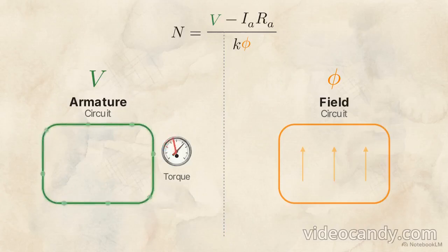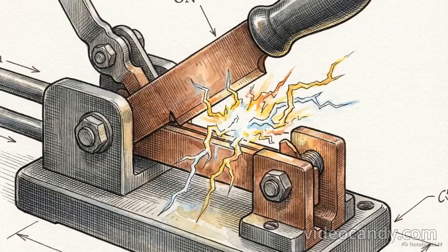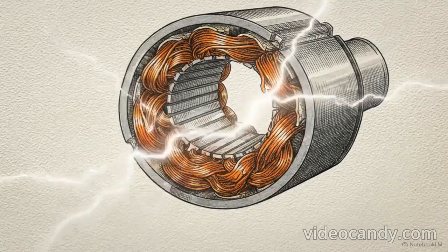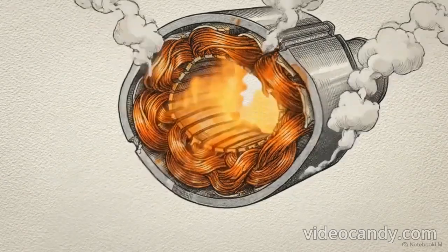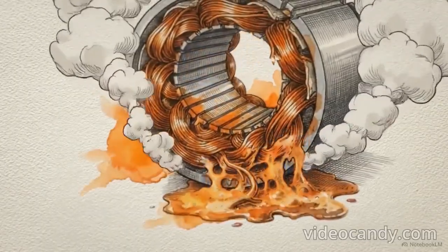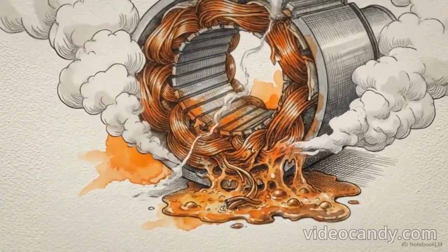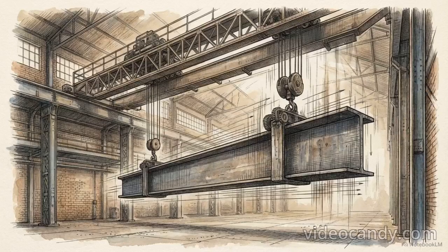Because the armature and the field windings are physically separate circuits, controlling them is mathematically simple. You can alter the armature current to dictate torque without interfering with the field flux. That separation presents a distinct challenge at startup. When a DC motor is at a dead stop, it generates no back electromotive force, or back EMF, to resist the incoming power. If you apply full voltage immediately, the inrush current will melt the armature.